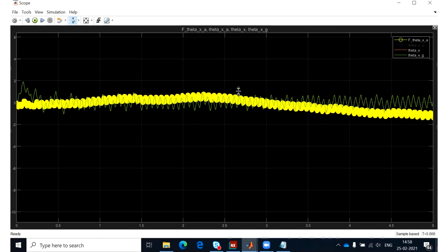And as you know, what you get from the acceleration when the system is shaking is not only the gravity acceleration, it is also the acceleration of the system. So you shouldn't expect that what you get from the accelerometers is exactly what you need, because as I mentioned in the IMU lecture I gave, accelerometers measure all the accelerations applied to the system.